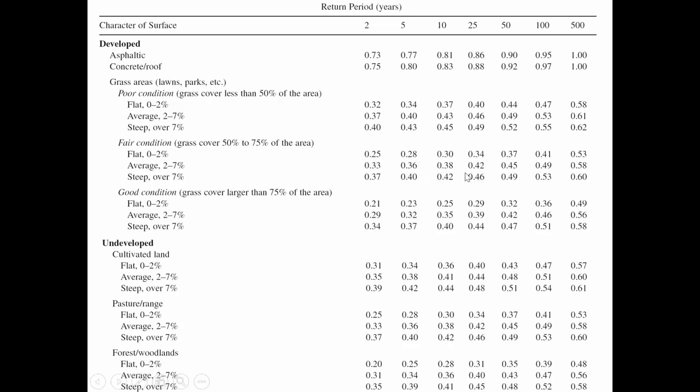And so what do we have here in West Virginia? We've got very steep areas. A 7% slope? We'll laugh at a 7% slope in West Virginia. I've got 40 and 50% slope watershed areas that sometimes I do models of. They're considered very flashy watersheds because when it rains, the peak comes through very quickly. Okay, so this is a nice resource in your text of C values for different